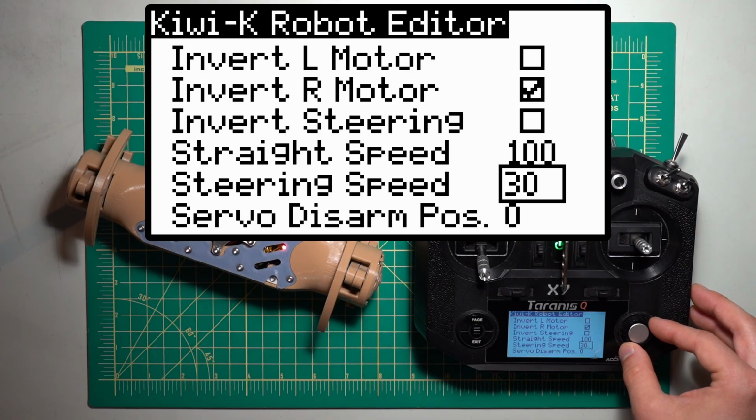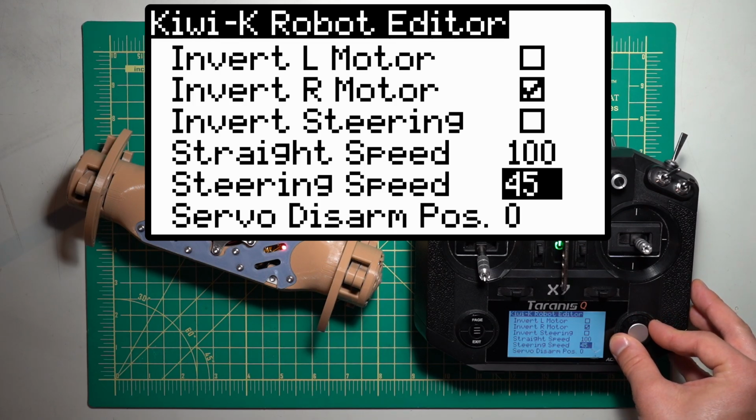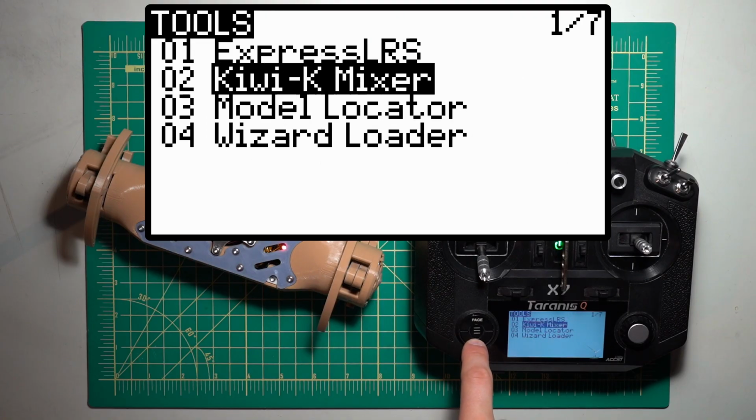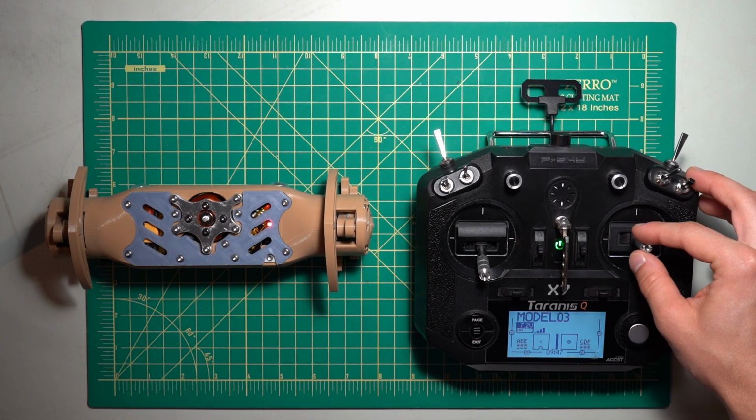While I'm here, I also feel like making the robot turn a little faster. I'll select the steering speed and turn it up a bit. When I press enter, it rewrites the mix with the faster turning speeds. Now, if I exit the editor and test my robot again, you can see that it drives forward correctly and turns in the correct direction.